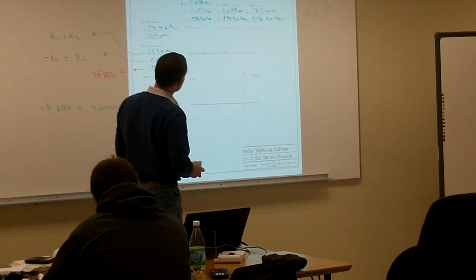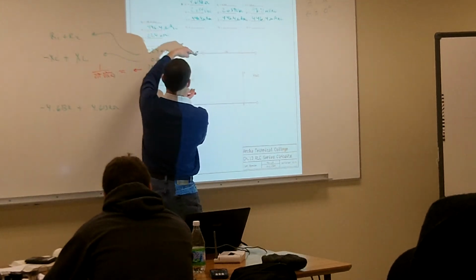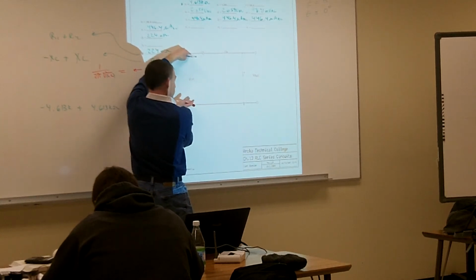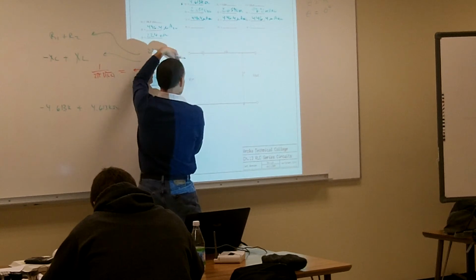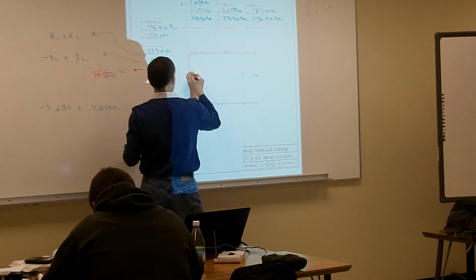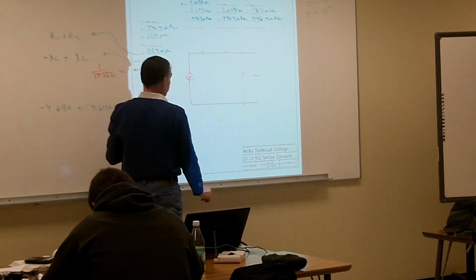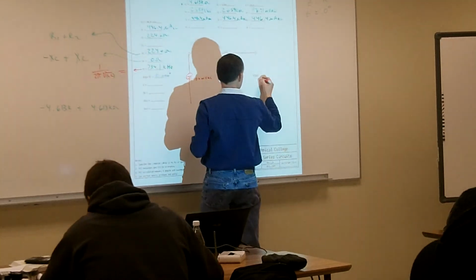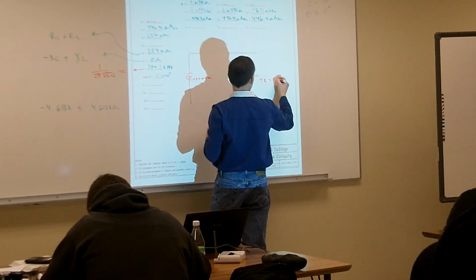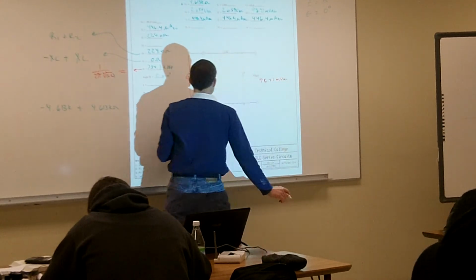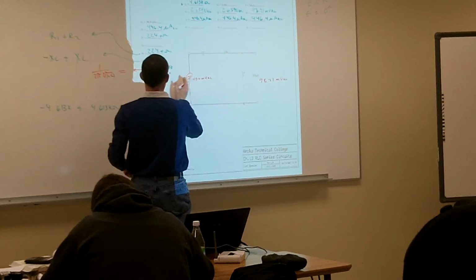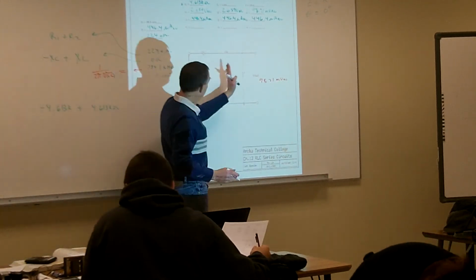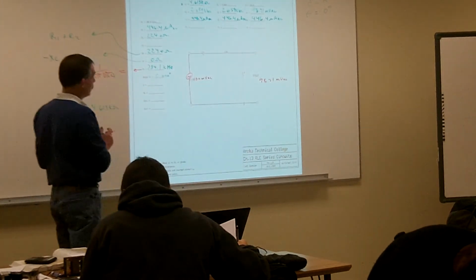All right, so now we have all our voltages, and so here I am putting in 100 millivolts AC. A lot of times this is what our filter circuit looks like. They don't even show you the source voltage or anything like that. They just assume this is where my VIN is, so it's basically having me hook up my function generator up to it, just like this. I put 100 millivolts AC into the circuit, and my V out is going to equal 98.21 millivolts AC. And that's only going to happen when I'm at my resonating frequency at 734.1 kilohertz. That's when my V out is going to equal approximately my source voltage.